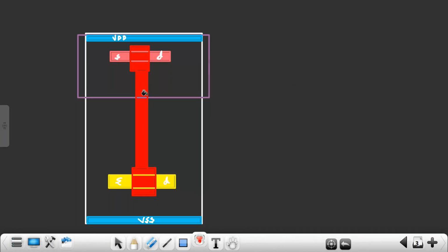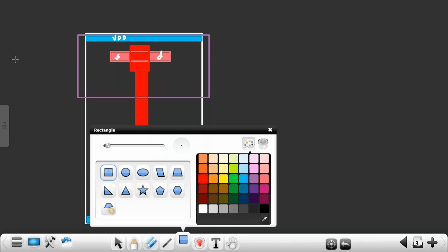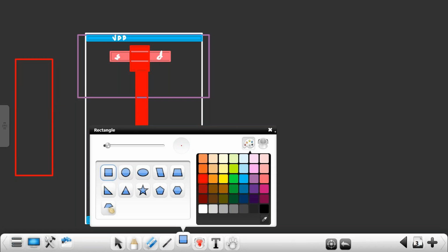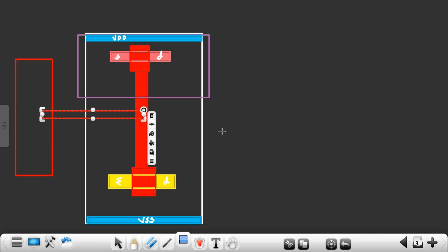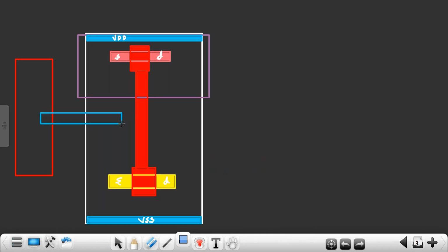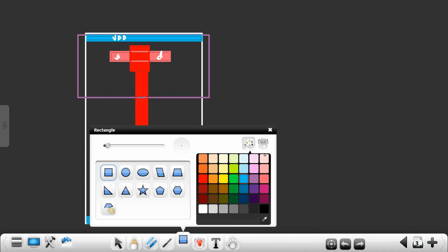So your gate is polysilicon. For example, if you have a previous cell layout, that layout you have to connect to this layout. Output of this you should connect here. So you will connect with what? Metal layer, right? But this is a polysilicon. I cannot connect directly. What I will do is give one connection here, a metal connection to this polysilicon.